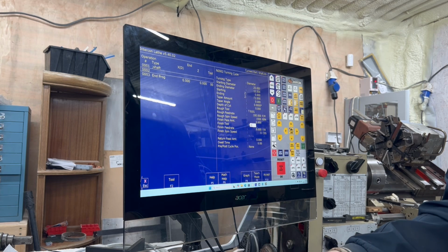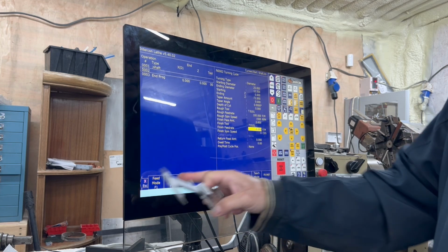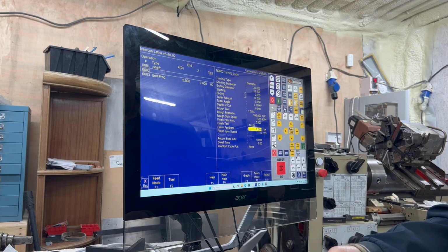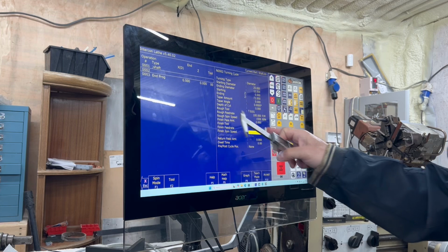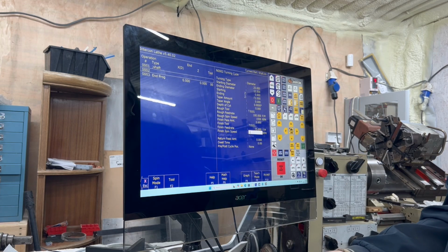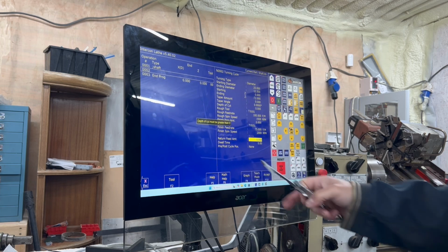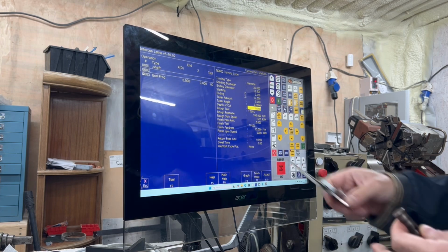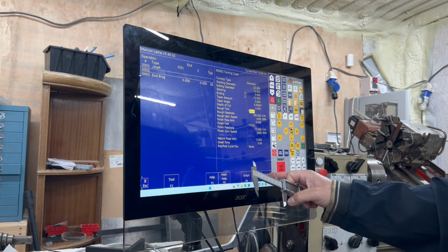And then a finish tool amount. We don't really care too much about the surface finish, but we can do the final cut at, let's say, 75. And we will do spin mode there, RPM. So let's go up to 2000 there. And that should be fine, except depth of cut. Now it'll give us a warning because we didn't set a depth of cut. I'm cutting into steel, not aluminium, so I'm going to be careful. I'll do 0.5 cuts, there's no rush.